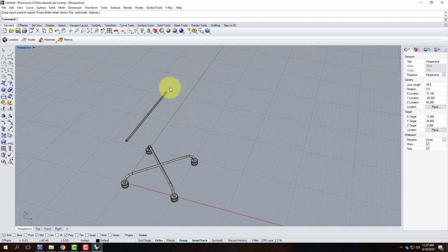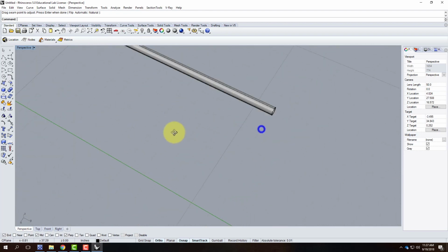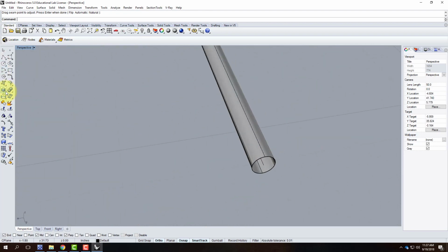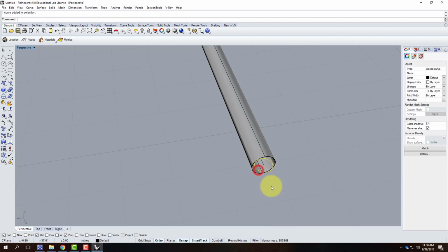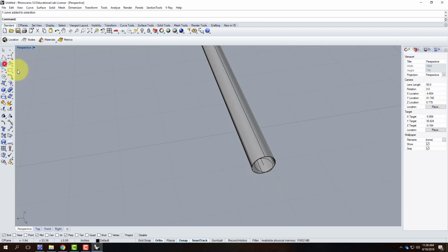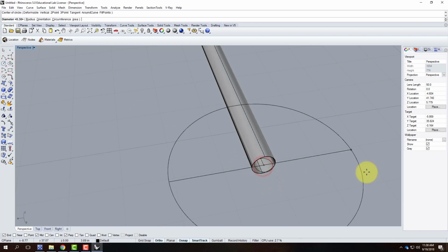So now that I have the rod, I need to do the little donut on the end. And so once again, under the standard primitives, there is a donut that you could do, but I'm going to do it with a sweep so that we emphasize the sweep, just different strategies. So in this case, I'll start with 2 curves. First one is the inner diameter. This would be 3/8 of an inch. Notice that it's smaller than the 1/2 inch, so it's meant to be a little bit smaller. So that one's 3/8. Then the outer one, in all honesty, I don't remember what it is.